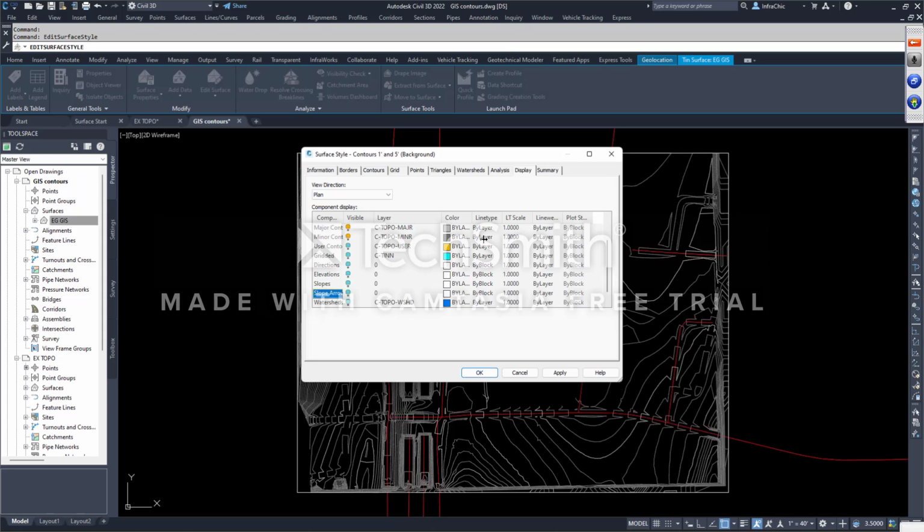Okay. There are a lot of other things up in this box, if you notice. On the display tab in your style dialog box, you have control of what is displayed when it's going to be printed. If you turn on anything in here and hit save, and you open up your sheet, then this is XREF'd into your sheet, and it will print it. Or if you just go to the layout tab, whatever is shown here is what will be printed. End of story.